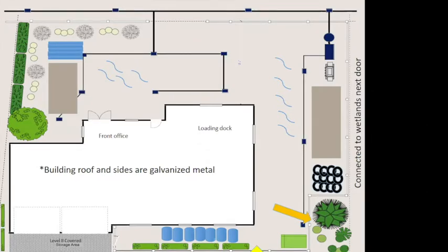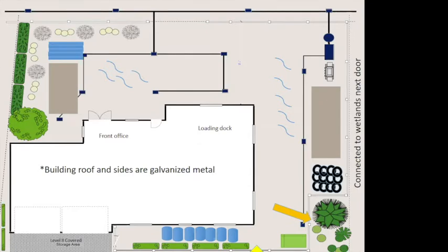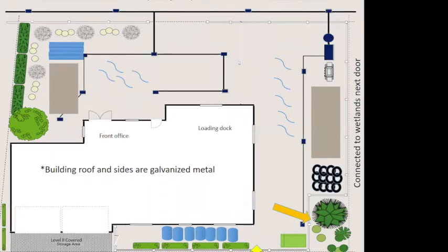I'll take the question. Yes, we worked with the Boeing Company to install some of that carbon fiber impregnated permeable pavement in a place in Tacoma called the Idea School. Although there's not a lot of big truck traffic, it is a live installation, so there is traffic going over it. We're taking core samples, and I think we're also doing runoff treatment analysis of their runoff, and some strength testing as well.